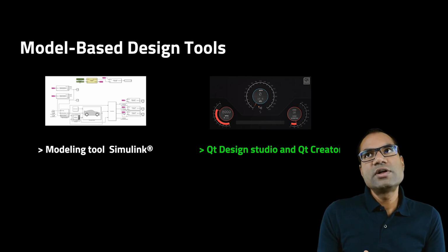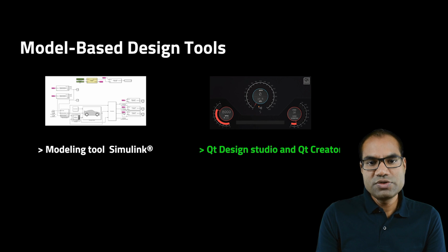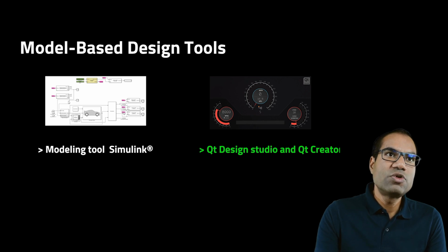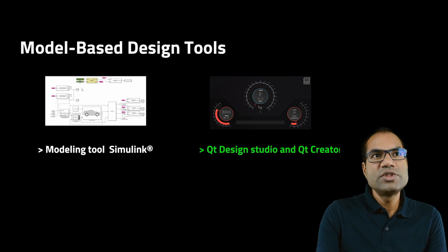So the next question is, I want to use model-based design. Now, which tools can I use? In the Qt ecosystem, we already have very good integration with MATLAB Simulink models. In the MATLAB Simulink model, you will find the Qt block set library, and by using it you can easily communicate over TCP with a Qt application.